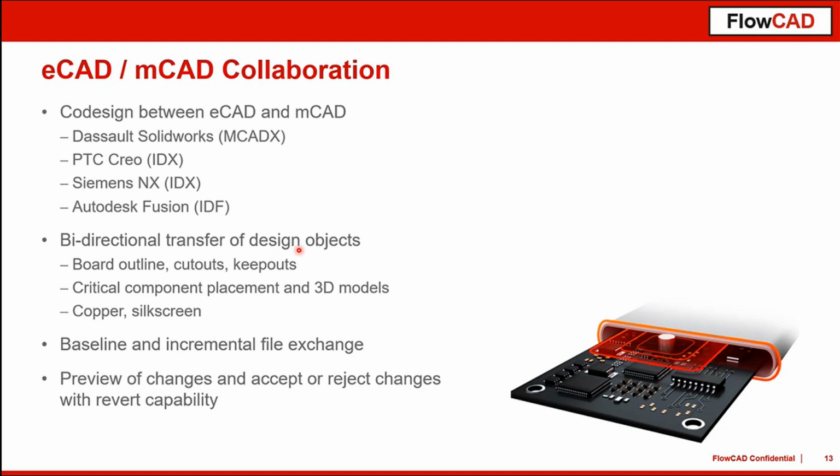Good, then we also have some new possibilities regarding the co-design between ECAD and MCAD. What was already inside of the old PCB editor was this IDX, IDF interface, DXF import for sure. And now in addition, we have this SolidWorks interface, based on the MCAD X format. The basic usage model is similar to the old IDX-based interface.